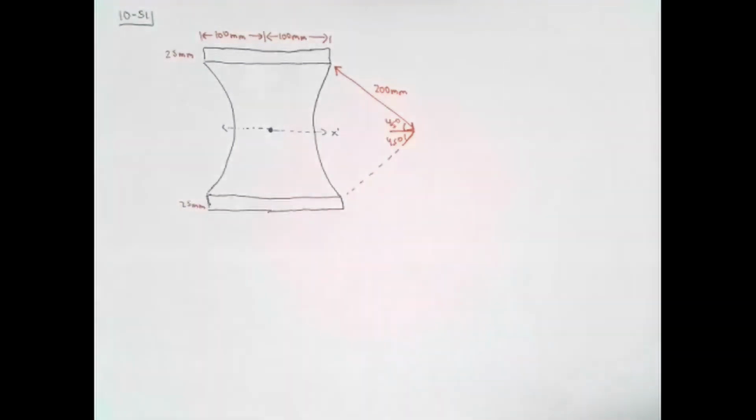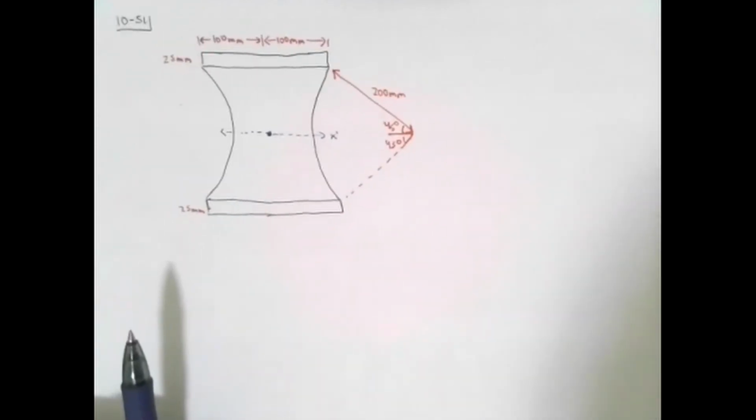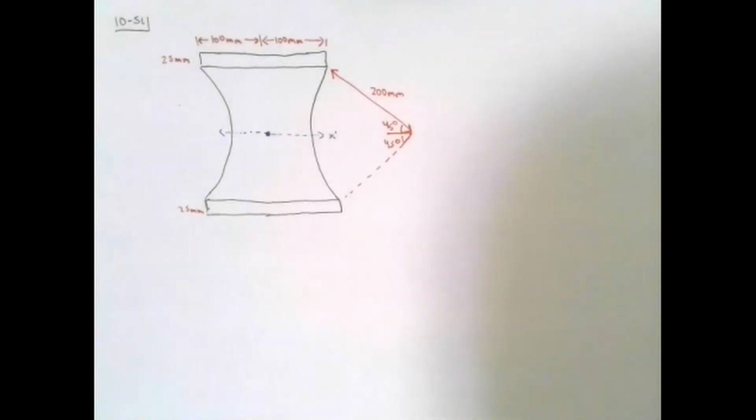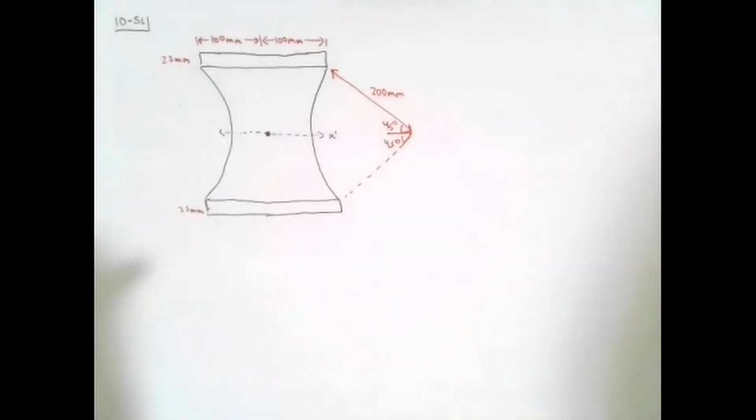So here's what we're going to do, and hopefully this will allow us to understand a little bit better how composite moments of inertia work. You may recall that when we had an area, such as a rectangle with a hole cut into it, we would calculate the moment of inertia of the rectangle, and then we would calculate the moment of inertia of the circle that forms that hole, right? However, we would subtract that moment of inertia of the circle. Why? Because the circle actually isn't part of this element, okay?